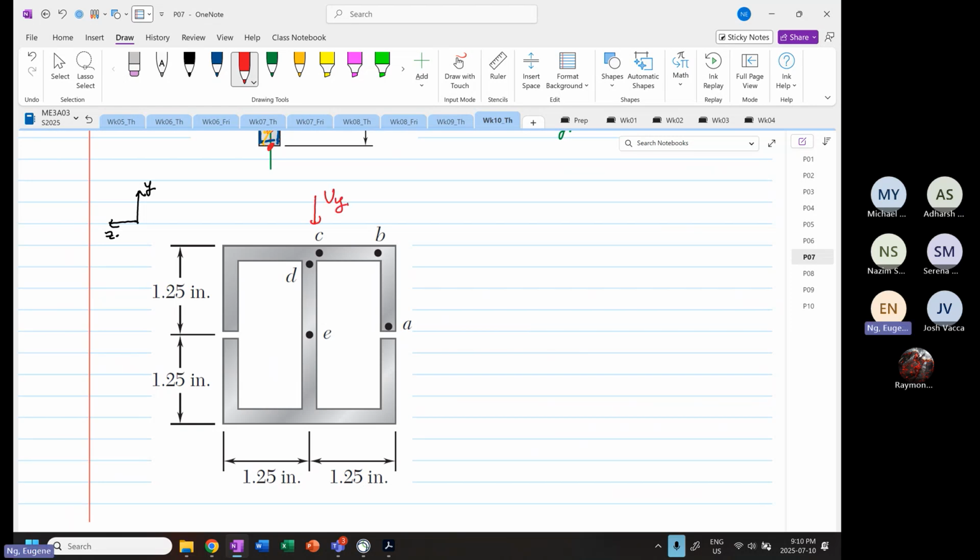The first thing you have to identify is where your major web is. I repeat again, you have to firstly identify where's your major web, and the major web has to be continuous from the top to bottom, and this seems to be continuous from top to bottom. The left and right ones are not, because they are broken.